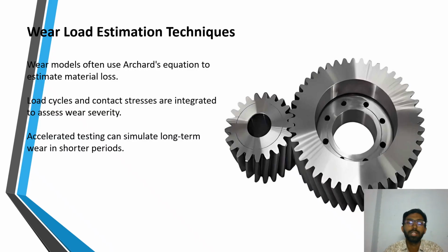Wear load estimation techniques. Wear models often use the Archard equation to estimate material loss. Load cycles and contact stresses are integrated to assess wear severity. Accelerated testing can simulate long-term wear in shorter periods. Here are the gears which are rotating. This is the driven and this is the driver.